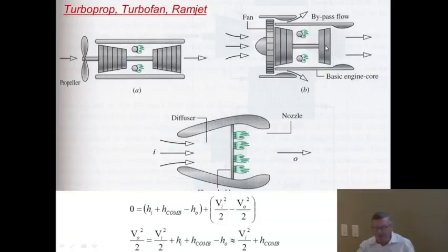And at that point, you can choose to look at the thrust of the engine, which is then the sum of the kinetic energy in the bypass air and in the turbine air, or you can choose to calculate the work that's put on the fan separately from the work that goes into the turbine, the compressor and the turbine drive both.